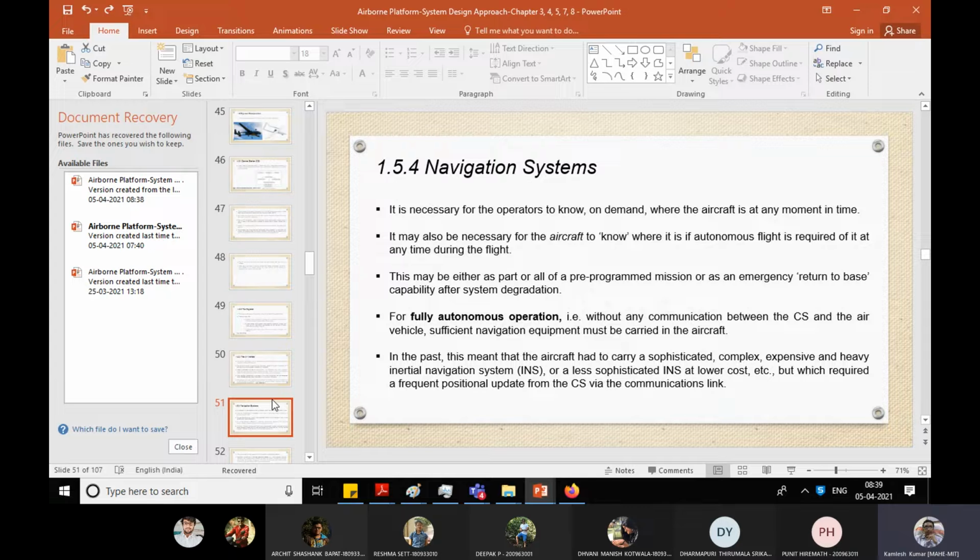Then, predicting from your reference point using the speed of the aircraft and time, integrating further, you then provide similar data again to the aircraft for calibrating. So this was very complex, expensive and heavy as a system, because these activities had to be completed on the aircraft on board. Otherwise it is very tough, because inertial navigation systems will give you error with time. You see twice integration is there, and with every integration error will be there, and if not calibrated within a short period of time, that error will increase and become very large.